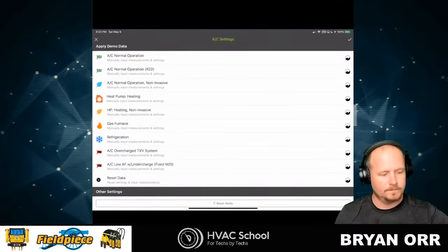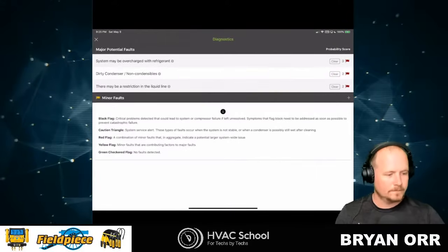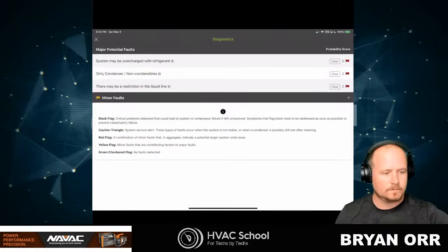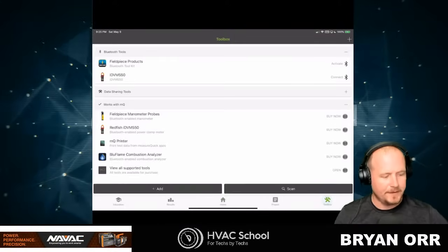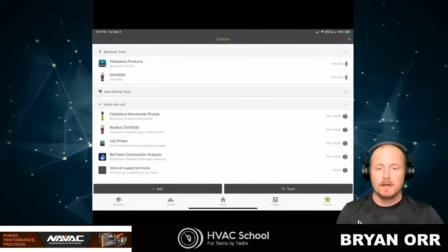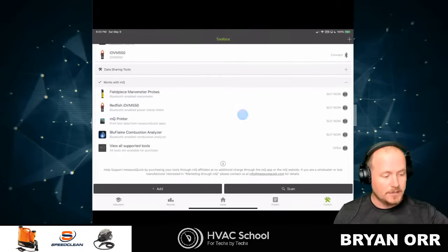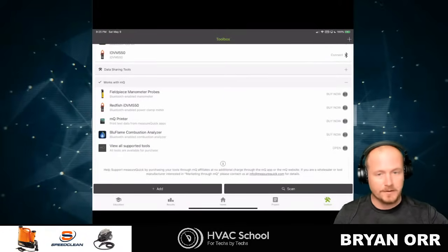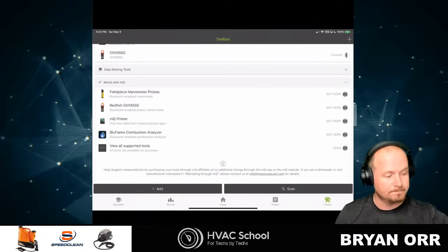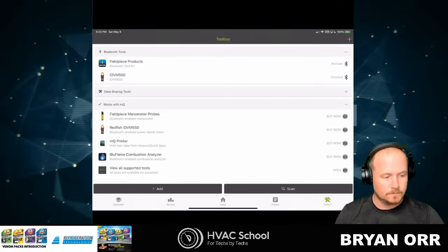And we've got Bluetooth tools: Testo, Fieldpiece. What is the other one? Not CPS. UEI. Yep, UEI. And I like the UEI air probes. A lot of our technicians use the UEI air probes. They're nice, especially in our market where we've got a lot of ductboard, and it's a smaller, thinner probe. So you can play around with it, see what you like, and go from there.